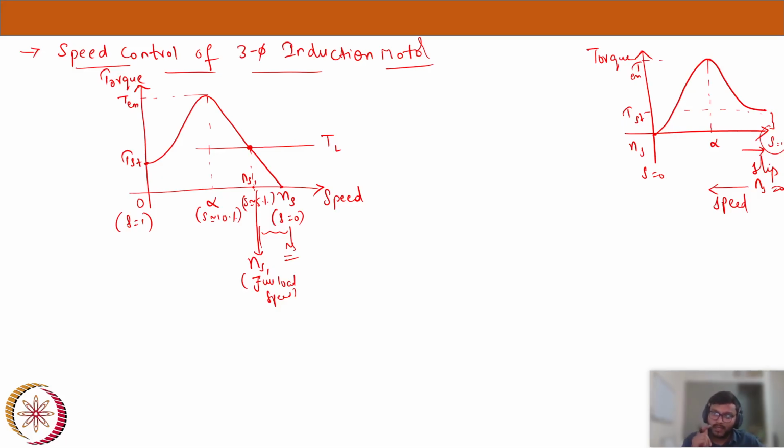The point we have to observe is that for a slip ring induction motor, by changing the rotor resistance we can achieve a very good speed control, which is also very smooth. By just introducing resistance in the rotor circuit, for the same maximum torque, we can get speed control. We will just see that. So this is also a speed control which we are talking about.